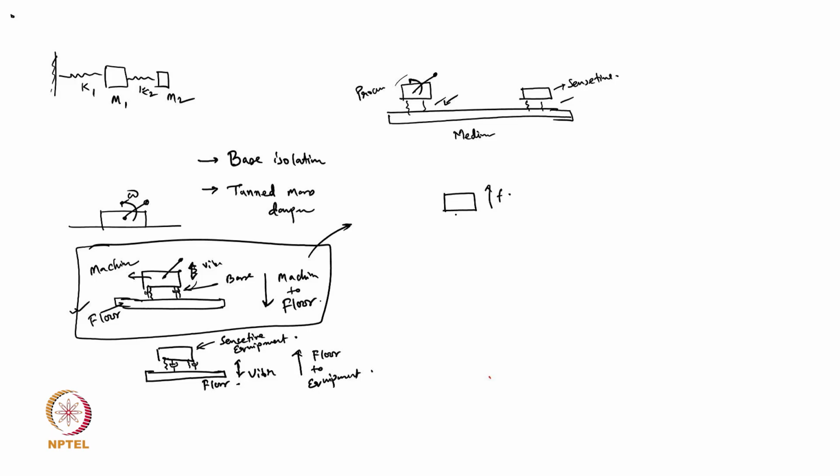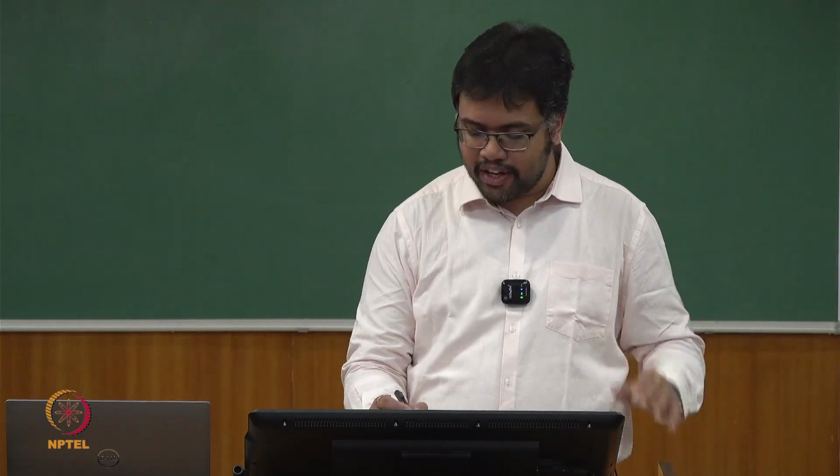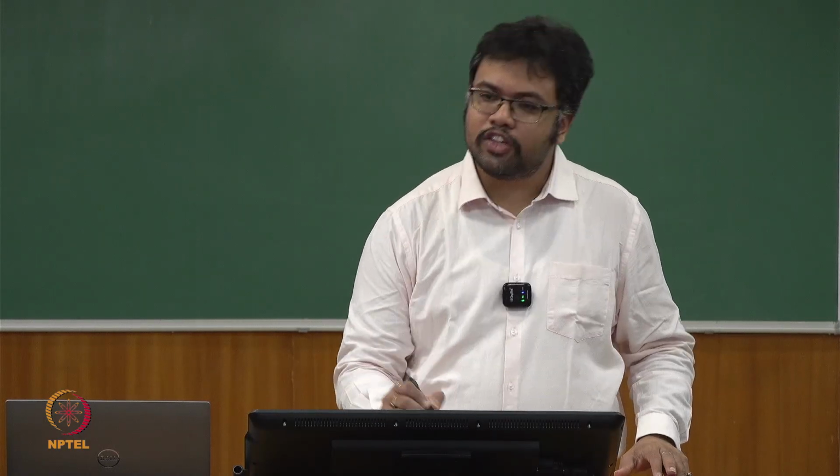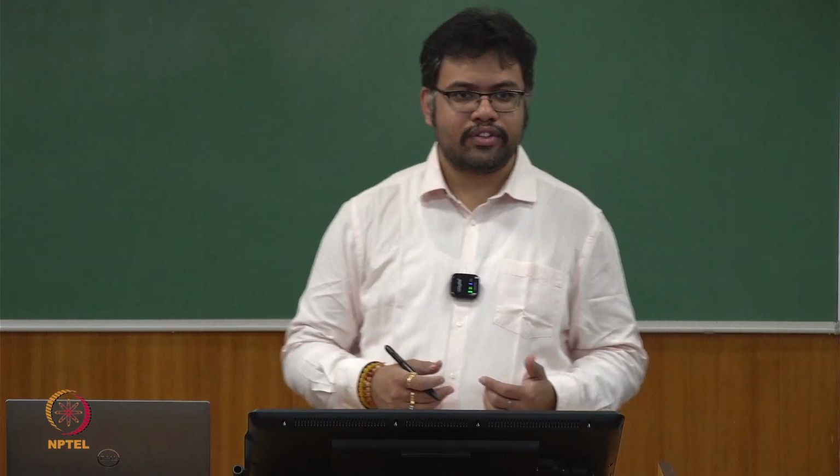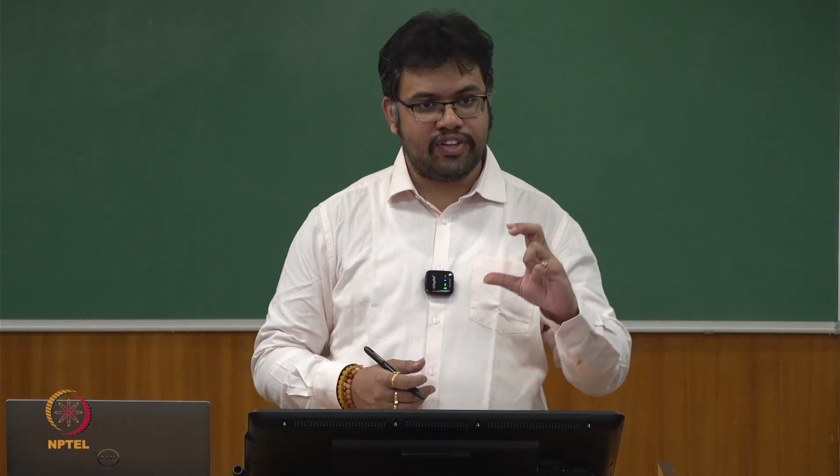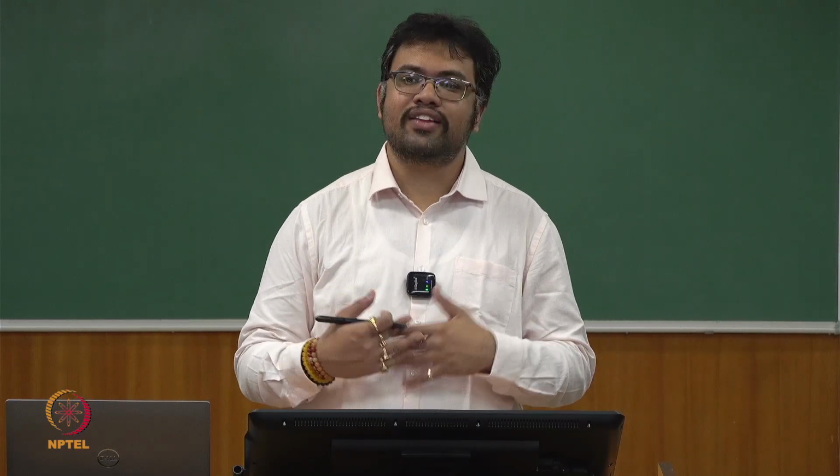Okay, good. Now it is supported on the floor, so some support. How can we model a support? Spring and dashpot. Perfect. Because spring will actually do what? Spring will provide the stiffness, and damping will provide some sort of dissipation. Okay, now next thing is the floor. How should we model the floor?